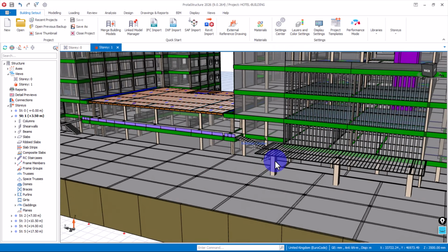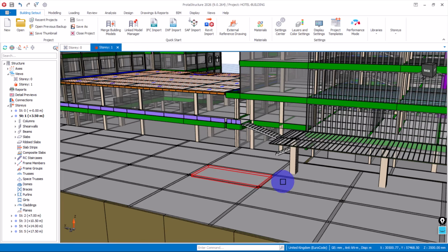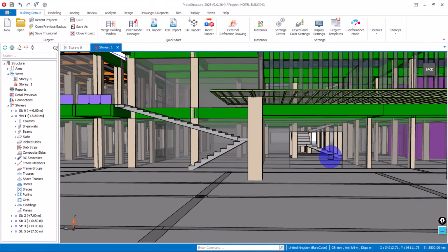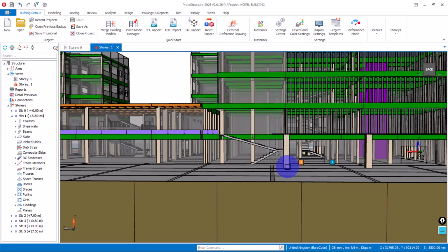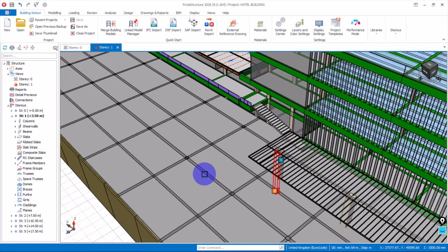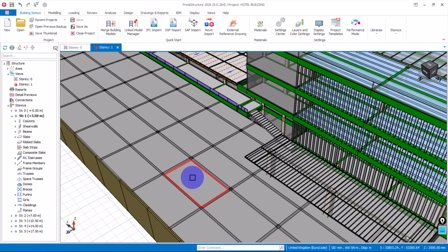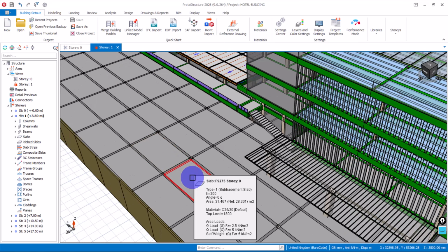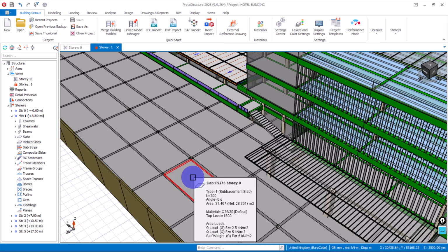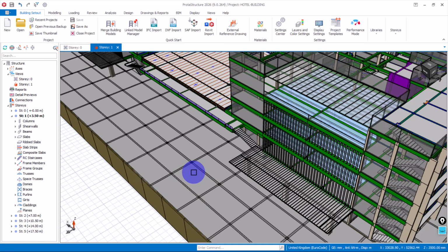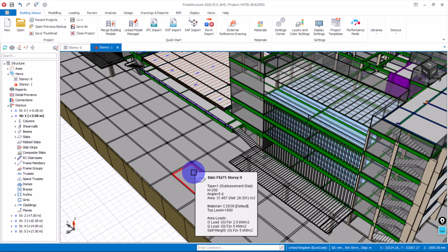For example, cars can park on this basement slab and then drop off customers through the entrance. So we have also added the car load on top of this slab, which ranges from 5.0 kilopascal to 7.5 kilopascal, knowing that it is non-heavy-duty vehicles, just normal cars, for example, Lamborghini, Rolls Royce, and all that.